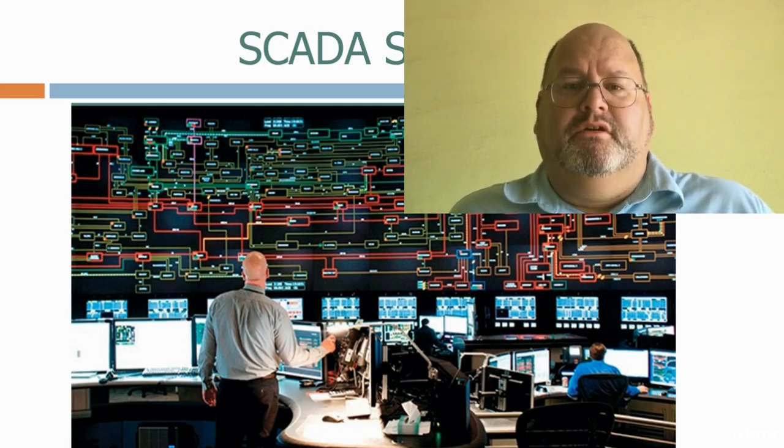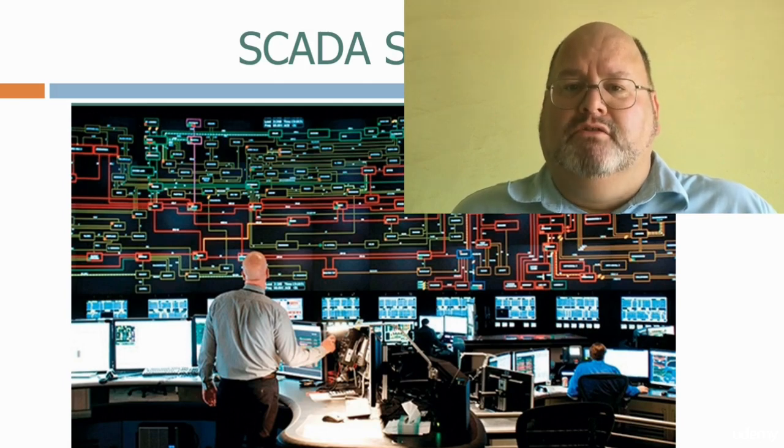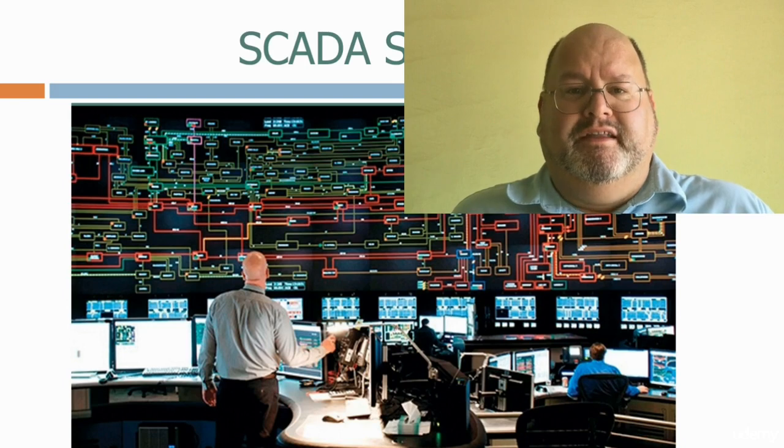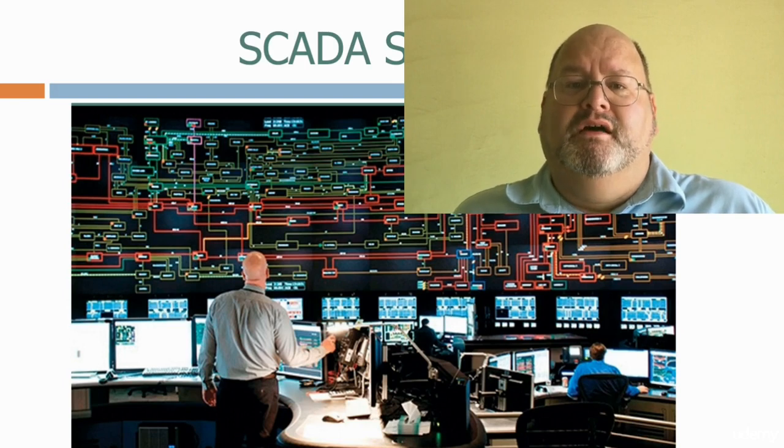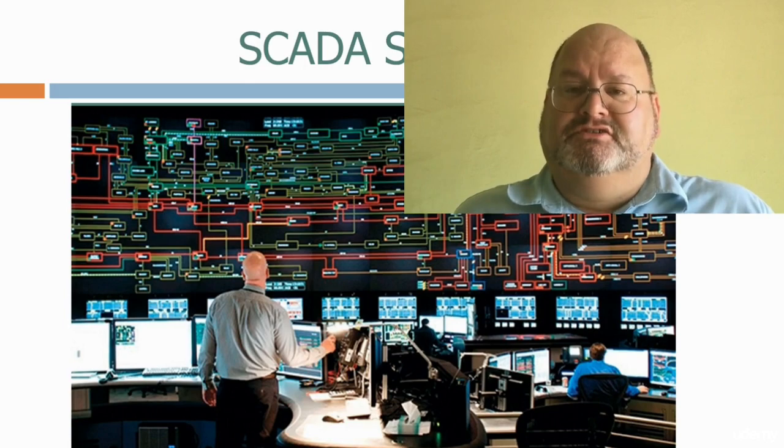The loads on the network follow a predictable pattern for most days, with the loads increasing in the morning as people go to work and industry start up. They then stabilize throughout the day before picking up in the early evening as people get home and make some dinner, before tailing off as the day comes to an end. The network controller needs to anticipate these load increases in advance, as the generation capacity must always match the load required to stop the system voltage collapsing.